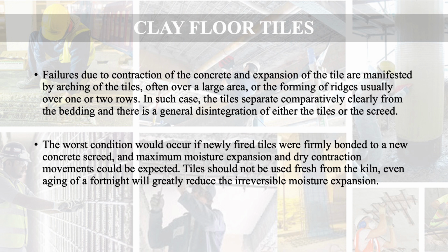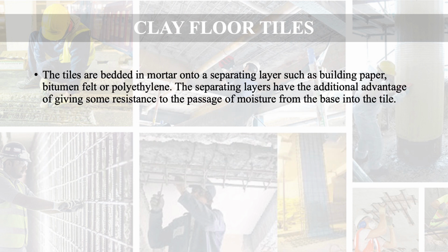Tiles should not be used fresh from the kiln. Even aging of a fortnight will greatly reduce the irreversible moisture expansion. The tiles are bedded in mortar onto a separating layer such as building paper, bitumen felt or polythene.